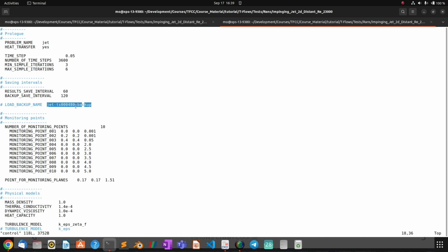At the beginning, the solution, we call it contaminated because it's very far from what the fully developed turbulent flow would look like. But anyway, the control points we talked about before, you can put as many as you want to analyze what's happening with pressure, temperature, velocity field in azimuthal direction, radial direction here. It's cylindrical coordinates here.